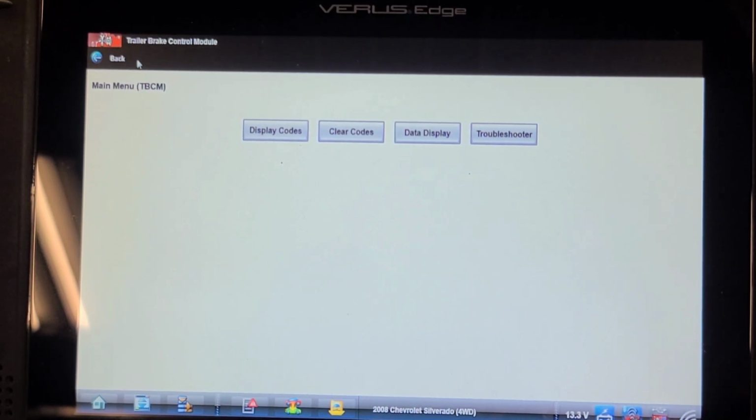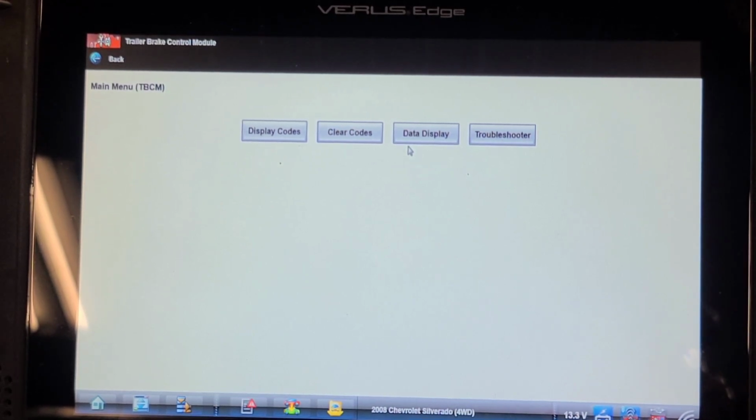Well, I think I'm going to try a trailer brake relay, because I don't see why it's not functioning. We've qualified the wires to it. There's only 6 wires and they all qualify. And the wires, the blue wire to the trailer plug and the trailer ground is good. At least it runs a 5 amp headlight. Powers and grounds to the trailer brake control module are good. The wiring is not in very good shape up there, but it's testing okay. So I'm going to get a trailer brake relay and try it.